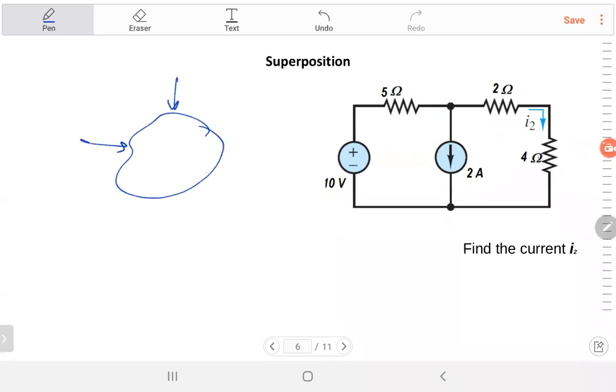like if you have a system and many forces like F1, F2, F3, and you want to find the effect of all of them, and you know that this system is linear. What you do is say, okay, F2 is equal to 0, F3 is equal to 0, and only apply F1, and then find the effect. Whatever happens, it may move something or cause deterioration, let's say move something for a distance. And then you apply F2, and you put F1 and F3 equal to 0, and find the effect of F2.